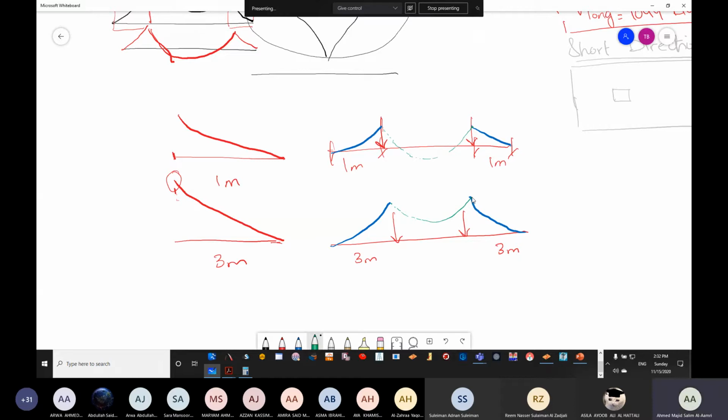Okay. So this is representing most of the cases of a combined foundation. We don't give higher dimensions at the edges. Now, why have we done it in our scenario? We have done it because there was a constraint that the width is 2 meters, so I had to increase the length. Otherwise, I would not increase the length; I would increase the width. Do you remember that there was a restraint of the width equal to 2 meters?